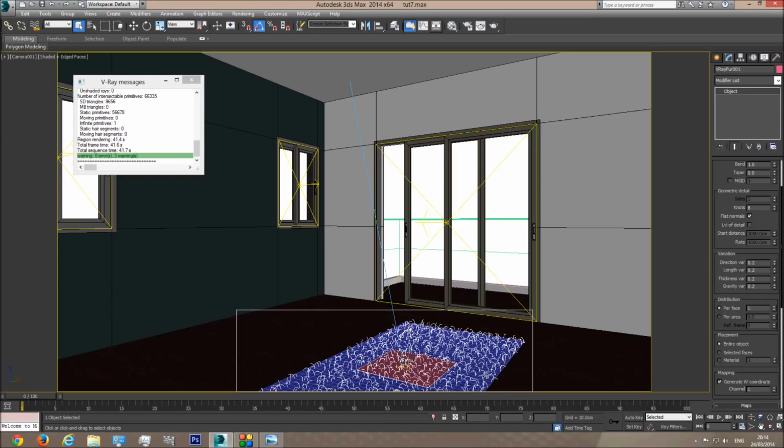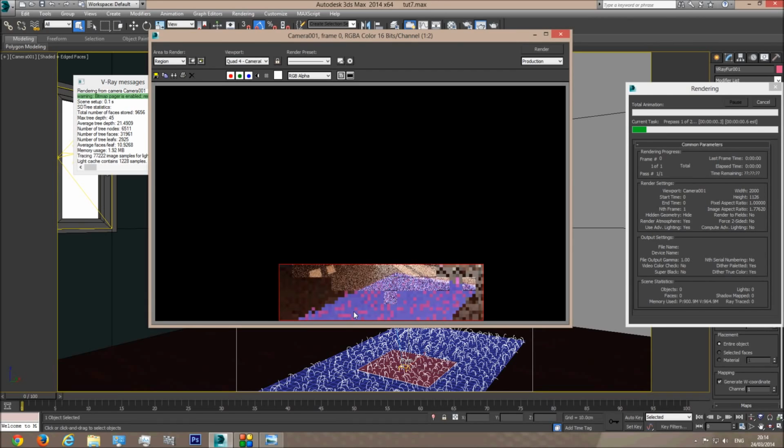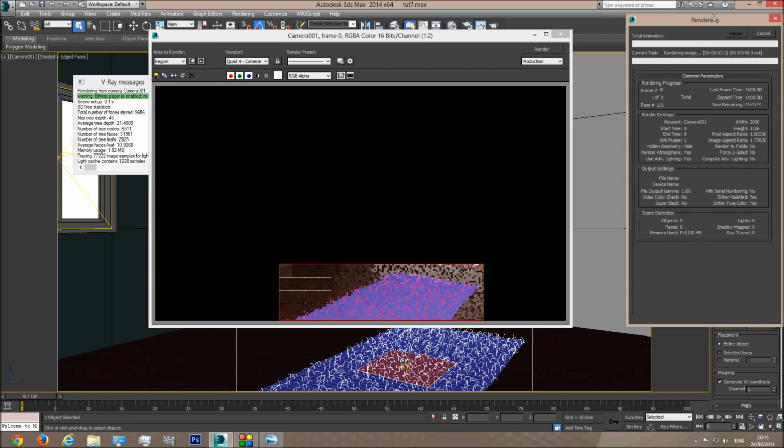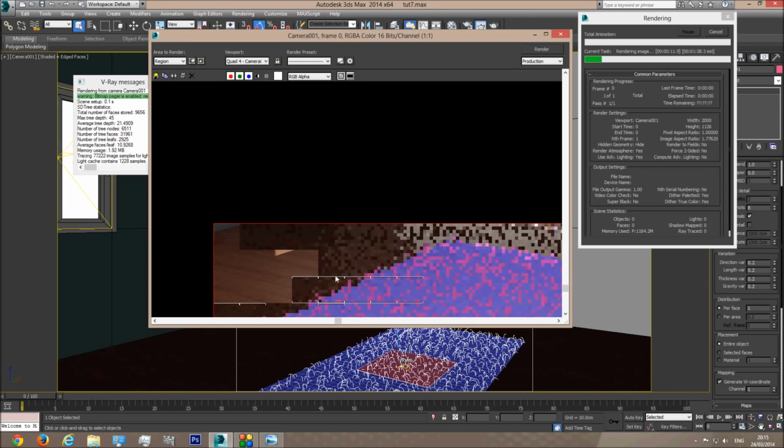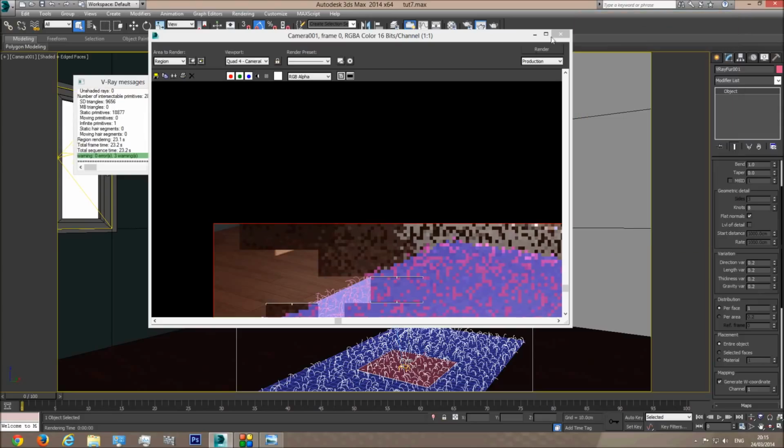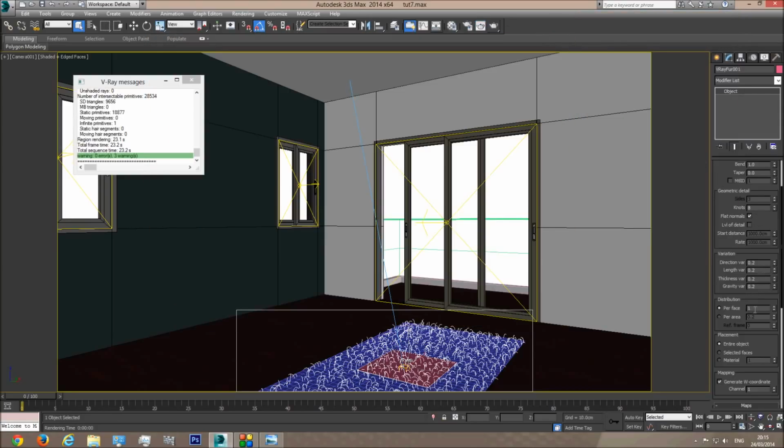what this will do once I render is create one hair in each square. Alright, so that's very few hairs, and we will have a very bad result. So we need to take this value way up. I'll just show you how it looks with one hair per face. Not enough, not by a long shot, so we're gonna make it way more, something like 200.